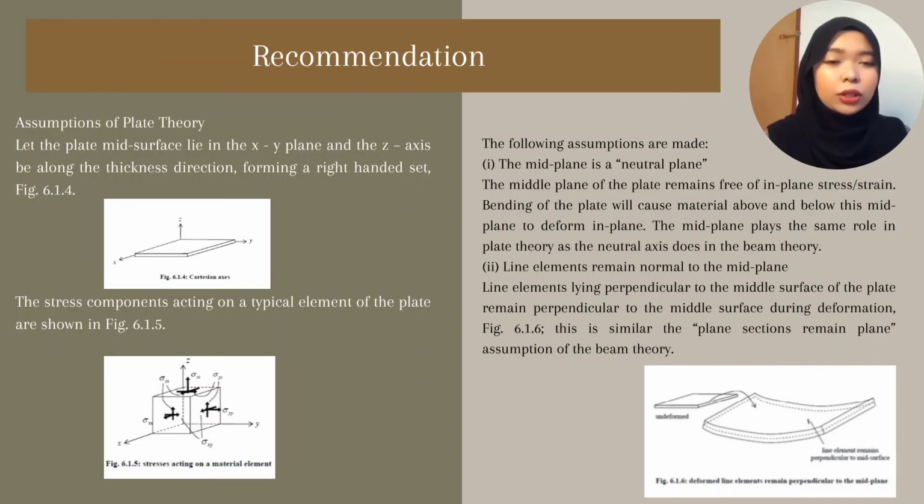Assumption of plate theory. Okay, we have a plate structure. Let the plate mid-surface lie in the XY plane and the Z axis be along the thickness direction, forming a right-handed set. The stress components as seen on a typical element of the plate are shown in figure 6.1.5. The following assumptions are made.